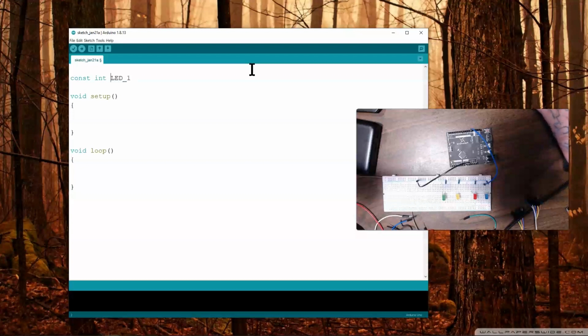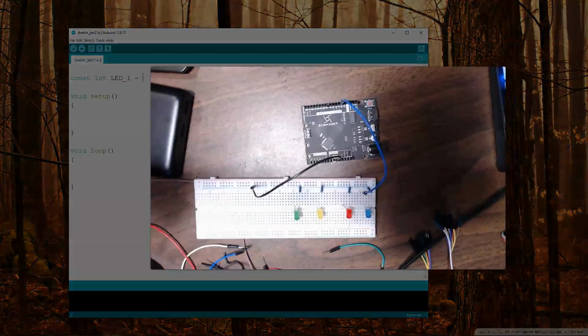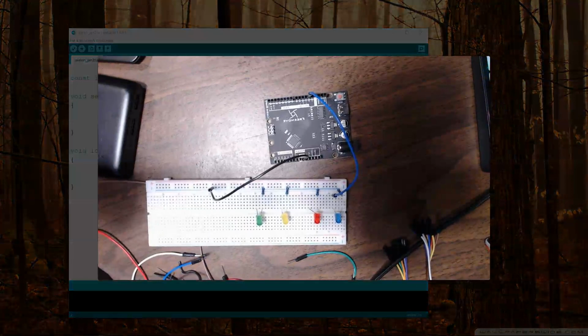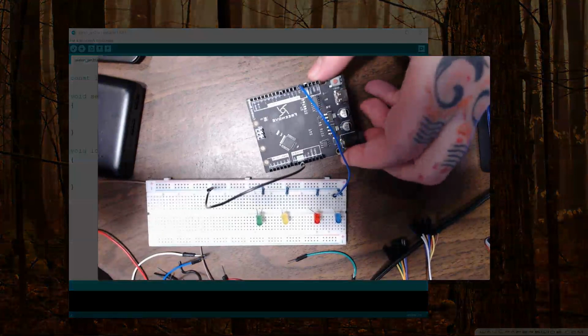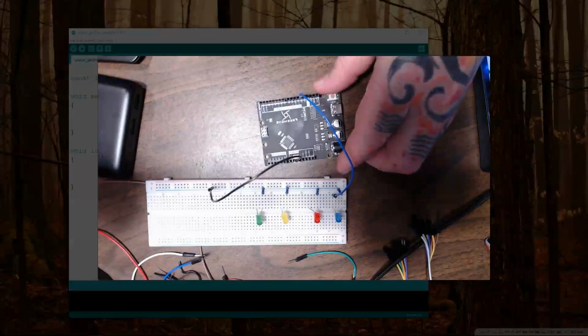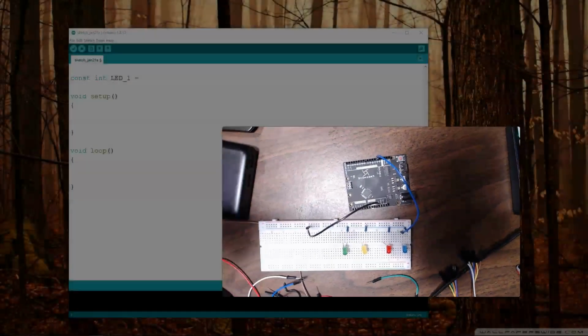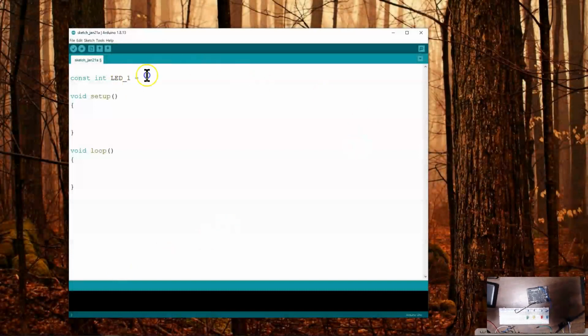I'm even going to say, yeah, let's do LED 1 for right now. We can see it's blue, and we can just confirm that whatever we put this to, we have to make sure it matches up to what we have it connected to, boom, pin 12. So pin 12, putting 12 there doesn't make it say that this is connected to pin 12 yet. It just means, okay, that's the number I'm using, and I'm saving it into this variable.